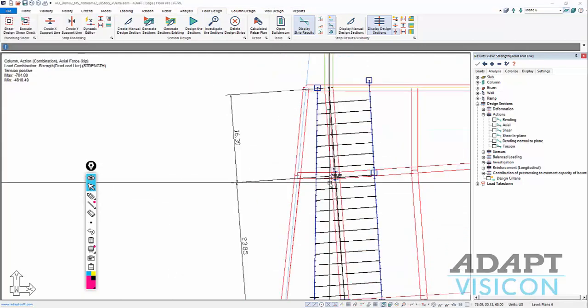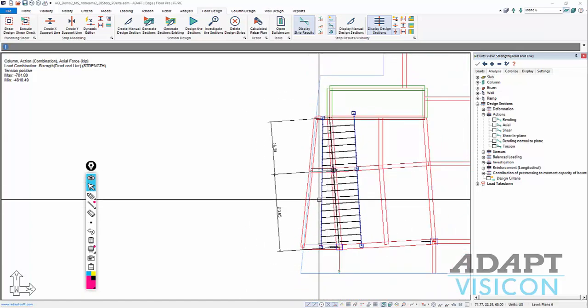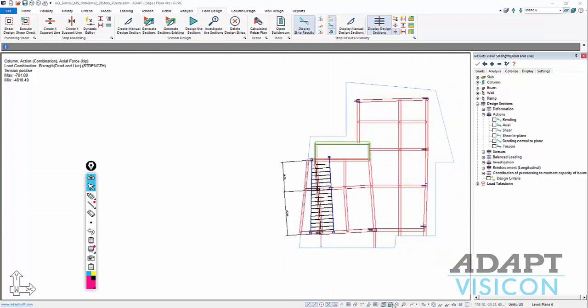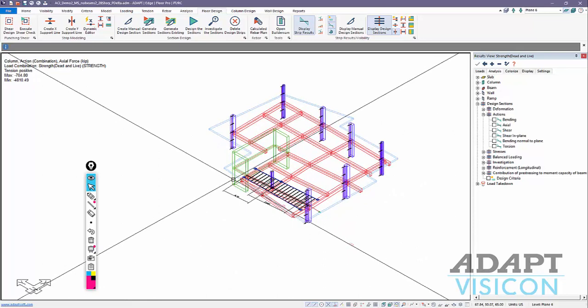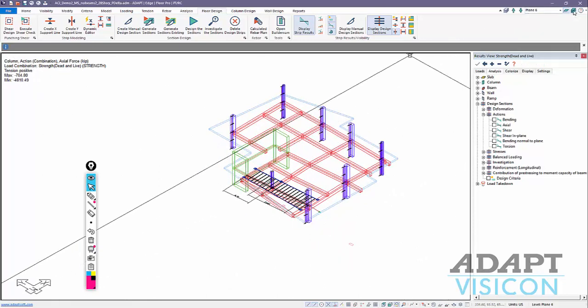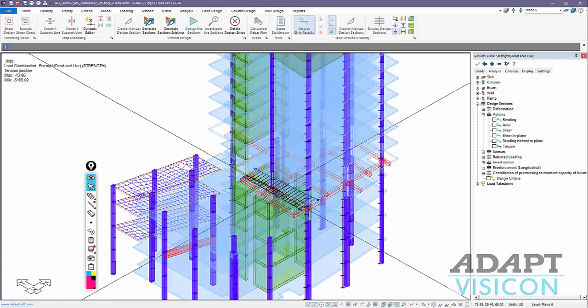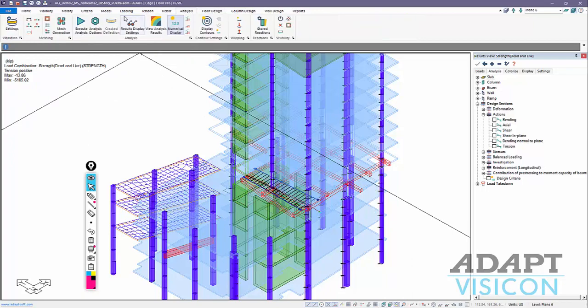Because we've entered a new component, which is post-tensioning, we actually need to reanalyze the structure. Otherwise, we don't get an updated solution for the hyperstatic actions from the PT. So this will require us to come back. Because we're first illustrating the direct method using global FEM results, we're going to go right back to global analysis. We now have some post-tensioning there, and we're going to analyze the structure again.